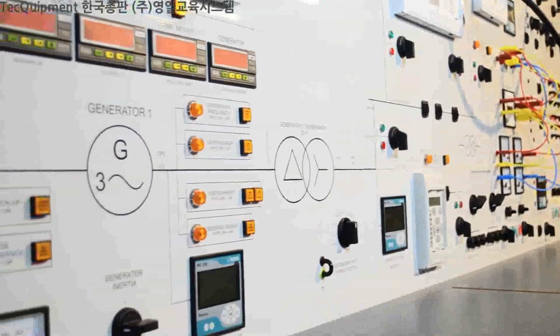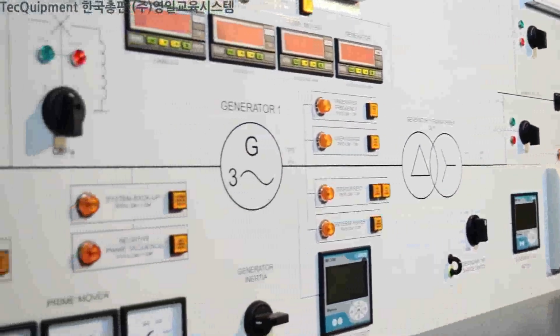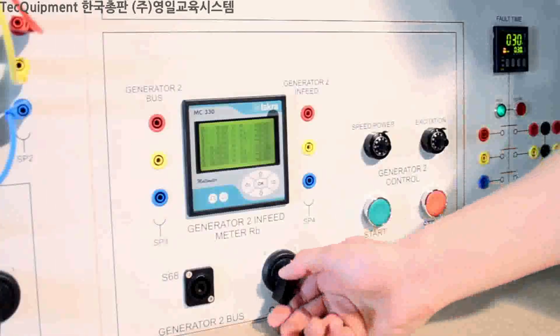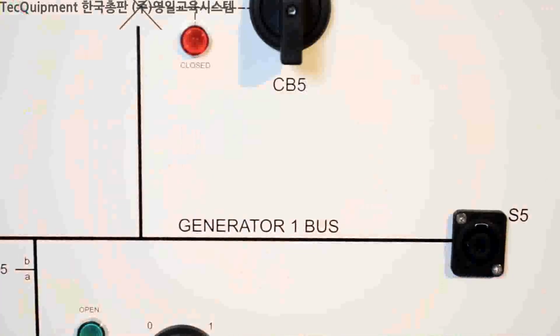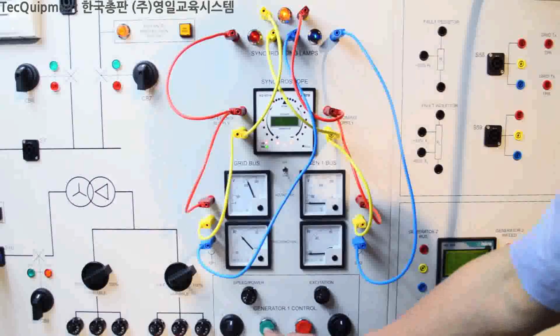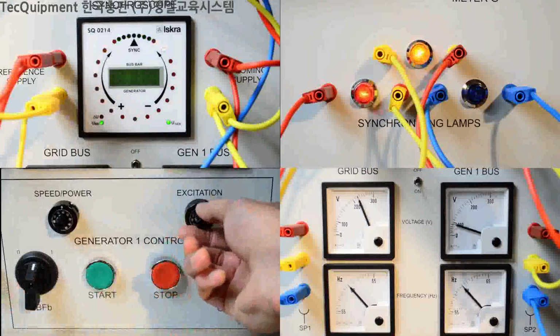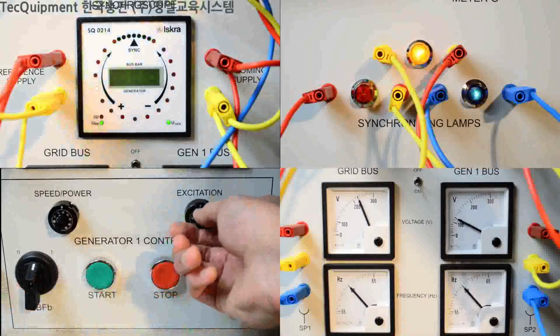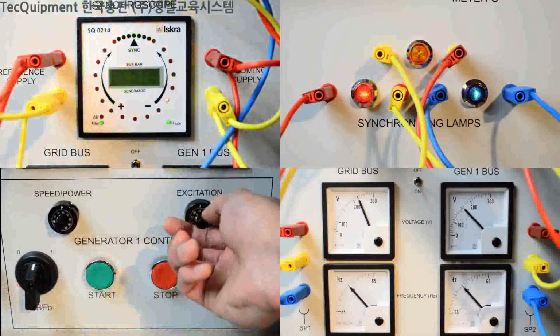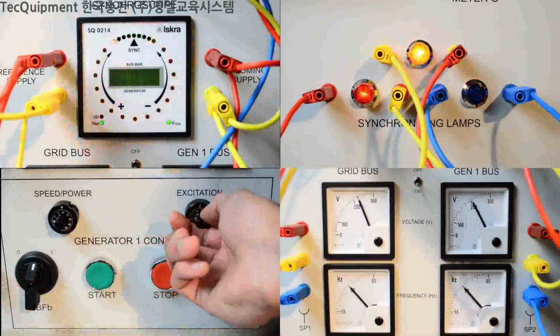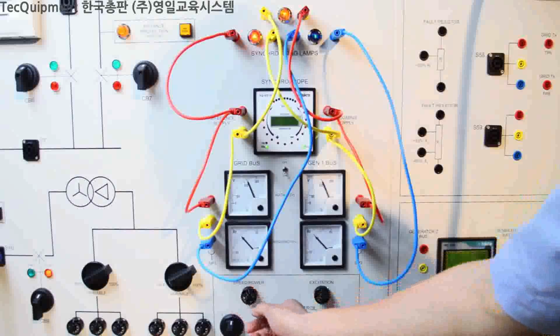Power input for the PSS1 can come from either the prime mover generator, mains grid supply, or a second generator, the PSS3. The output of the generator or the grid supply runs through transformers, which give the correct distribution voltage at either the grid bus or the generator bus. This then allows students to correctly synchronize the generator output to the grid supply.